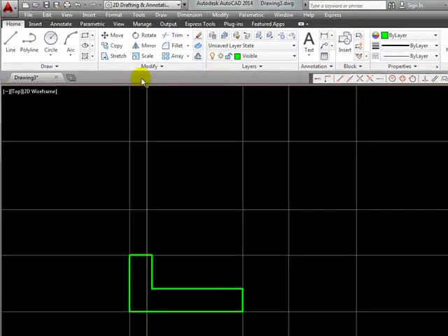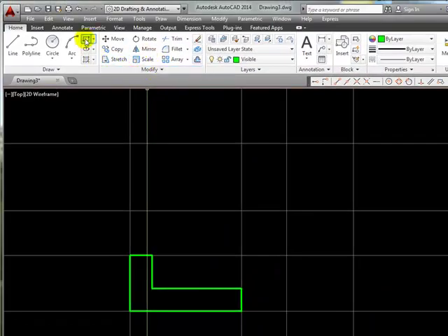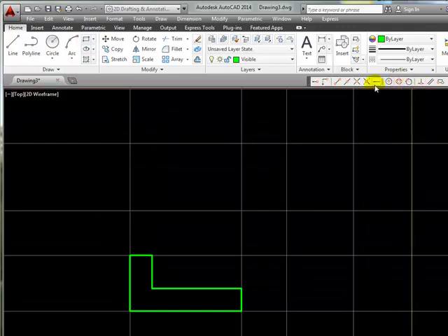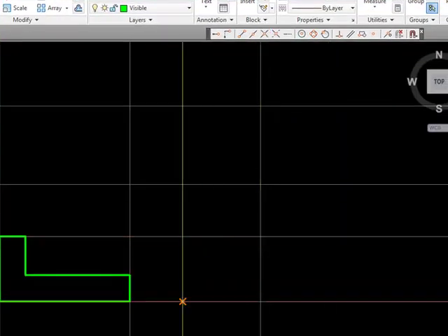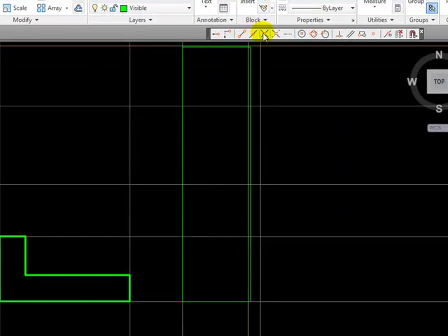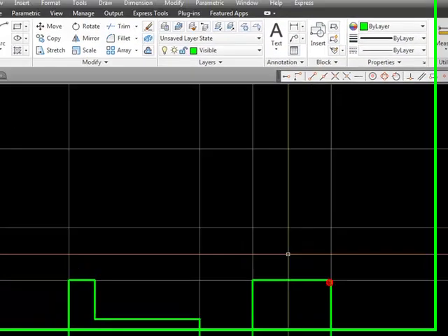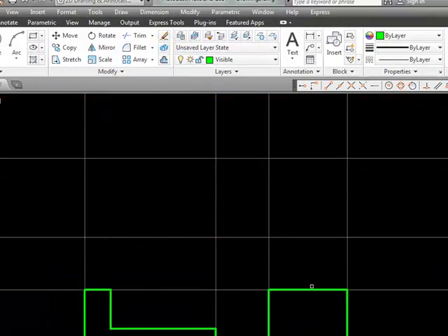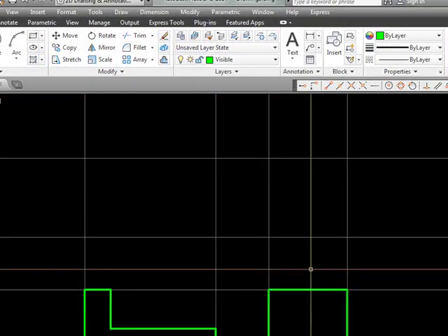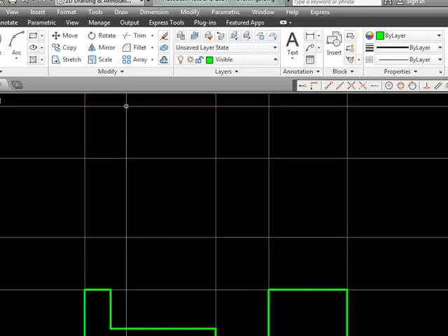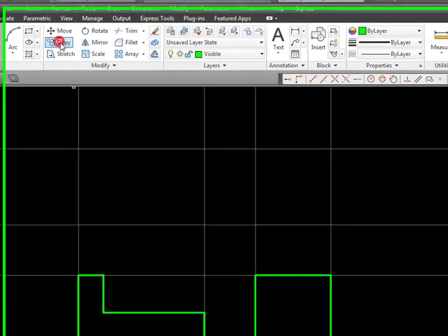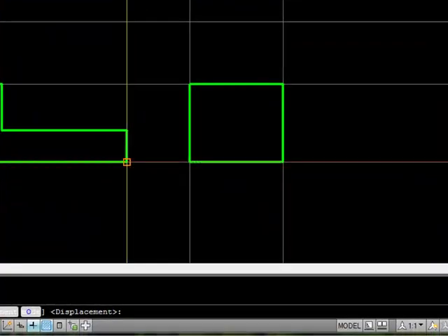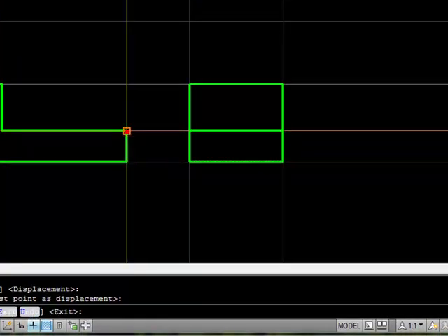The next thing I'm going to do is draw as much of the right view as I possibly can. So let's draw a rectangle from an intersection here to another intersection right here. I'm going to explode that geometry because I'll probably want to copy individual pieces of it. So let's copy this line, and I'll copy it from this point up to that point.